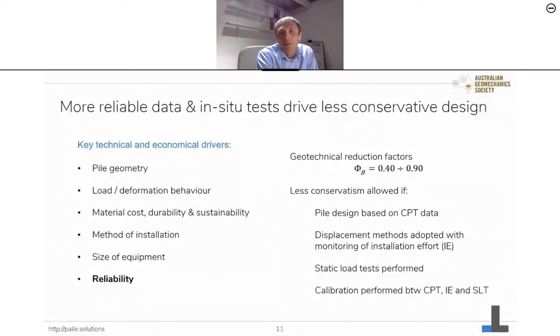Techniques that enable better verification of pile performance during construction combined with static load tests often lead to more optimal designs, and static load testing is typically considered to be providing the best quality information about pile performance. If trial piles are installed and tested in advance of the production works, meaningful savings can be achieved by optimizing designs. However, static load tests are expensive to perform, and pre-production trials are even more expensive. Therefore, a right balance between the amount of testing and the reduction factors is a crucial choice that has to be made.